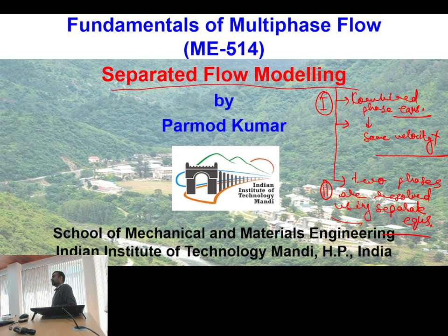Because of the more cumbersome approach, people did the very initial analysis using the very first approach. Okay, so in the very first approach, the combined phase equations were taken, but the only difference was that in the homogeneous flow approach, where we also had the combined phase equations, we considered that the velocities of the two phases are the same, whereas this condition is now relaxed, and it is assumed that the two phases have different velocities.